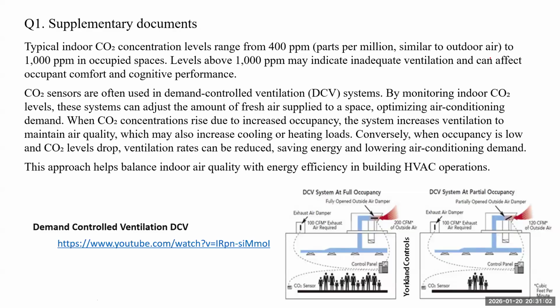For the demand controlled ventilation system, with a carbon dioxide sensor, at full occupancy it supplies the design outdoor air flow rate into the space.